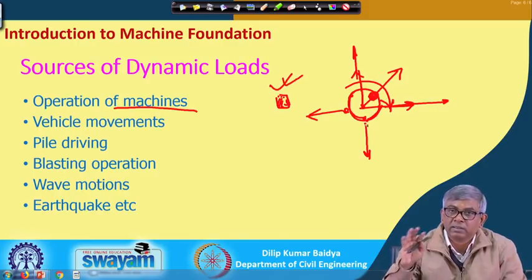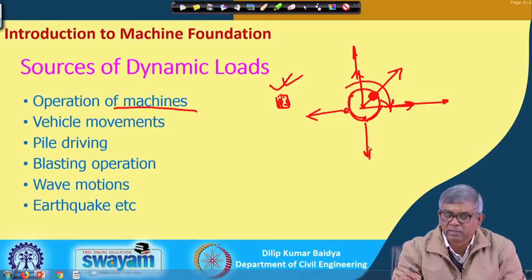And when there is a rotating machine which contains some amount of eccentric mass, because of the rotation of that eccentric mass, we know that centrifugal force will be there. Because of different positions, its magnitude will be constant, but it will have two components, vertical and horizontal, and sometimes it will be pure horizontal or pure vertical. I will discuss this later, how we can have a pure vertical motion because of the combination of two rotating masses.